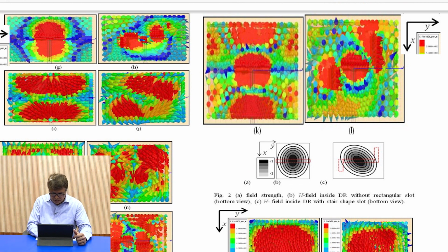If you see here, this is the feed mechanism, this is the slot. So, it was a rectangular slot initially, later on we have converted this slot into this. So, this is dominant, here the dimension length of this is longer as compared to this. Because of the higher dimension, we are able to get the dominant field excited and we are able to achieve this field rotation, that is known as circular polarization.